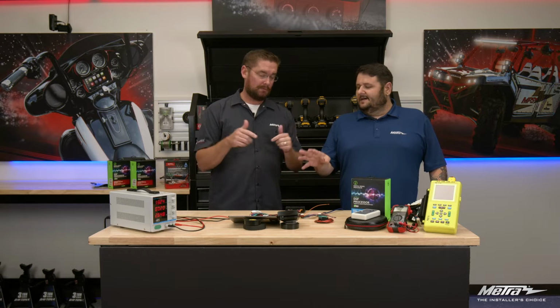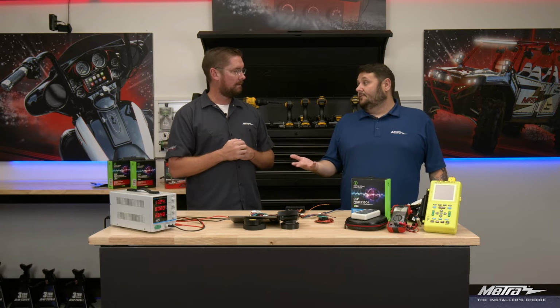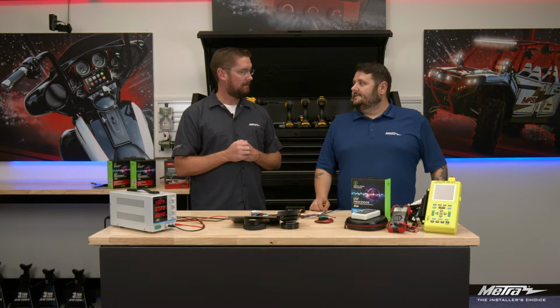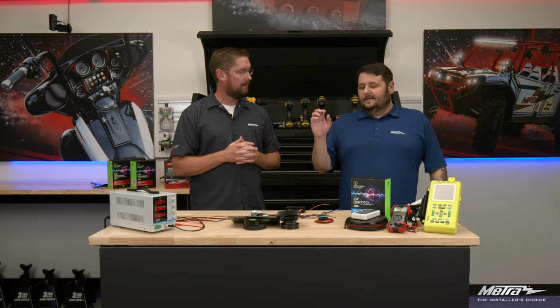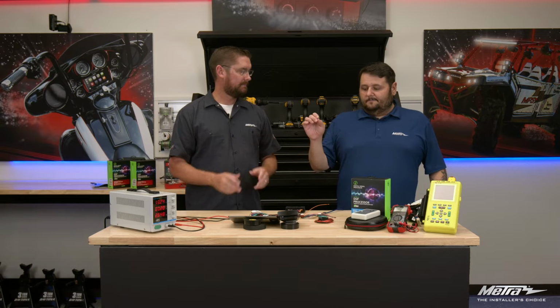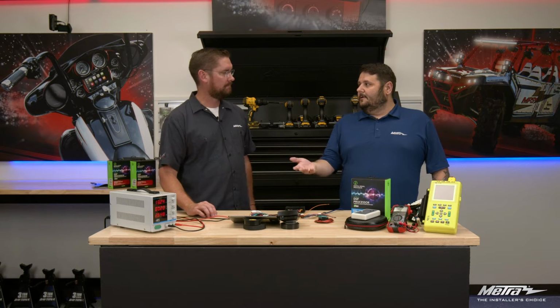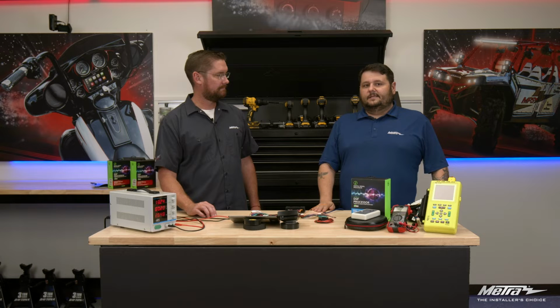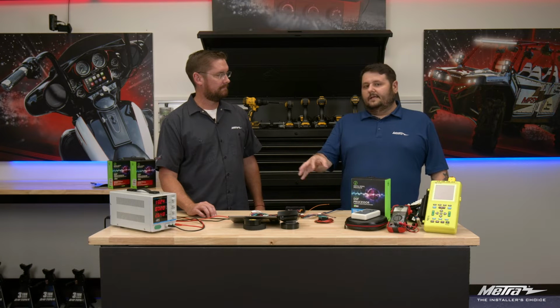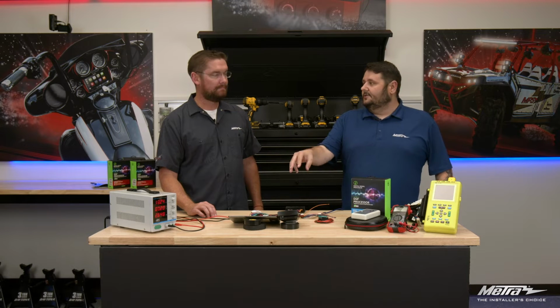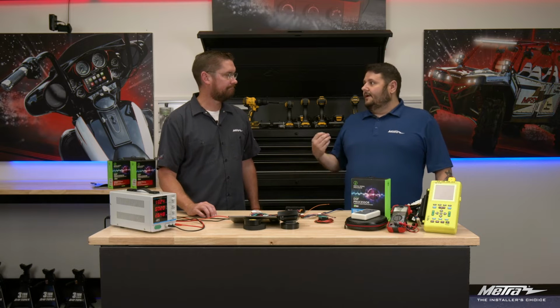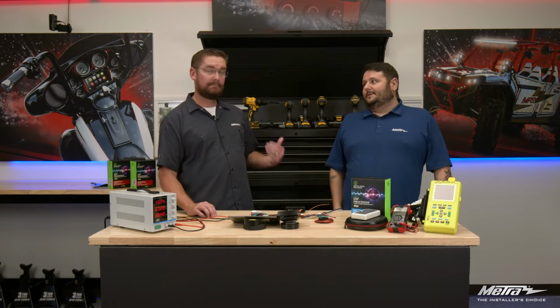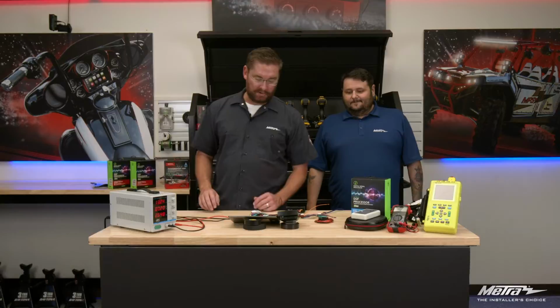Yeah, and so that's probably, from a technical standpoint or tech support, actually, the biggest misstep in setting this up. So I just want to take a second to call attention to that because it's super important. Because on these models, especially General Motors, that's going to be your chime. That's going to be your volume controls. That's going to be a lot. So take an extra second, make sure you're putting in the correct information to your DSP. That way you're getting the right communication from the DSP. That's right. Very important step.